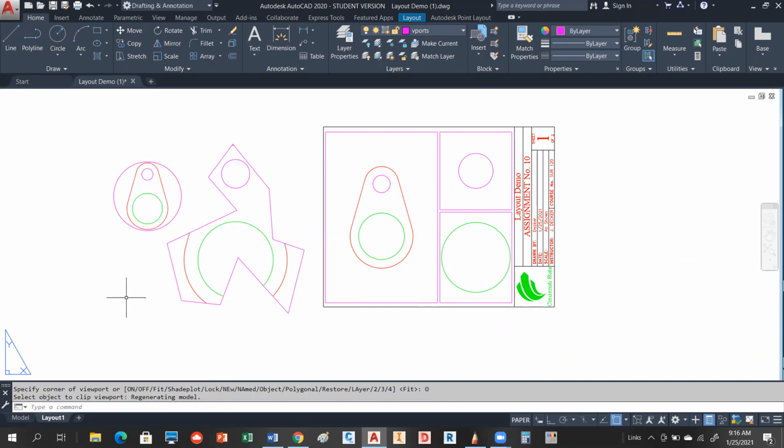And again, you might not think, well, why would I do that? But again, if this was a boundary and it had topo that was extending beyond it, this is a way of clipping stuff out so that you don't need to see stuff. And of course, then you go in and do the zooms just like you do the normal zooms. So that's a really cool function. For surveying applications, I actually do occasionally create irregular shape viewports. I would say probably 80% of the time I'm using the rectangular type of viewport, but that's not always true.